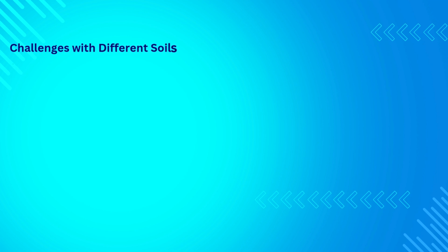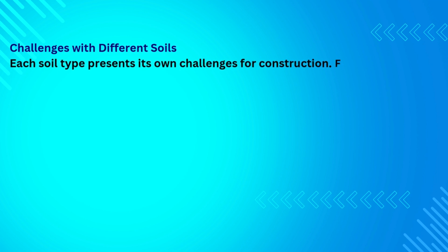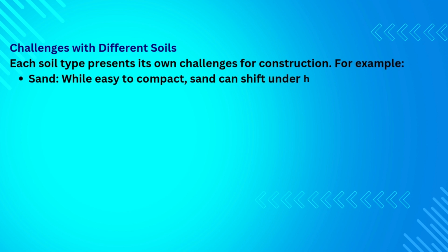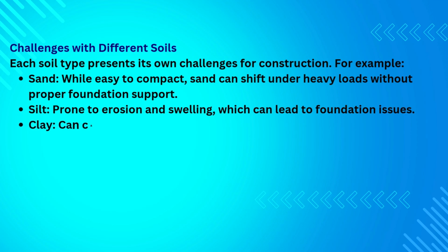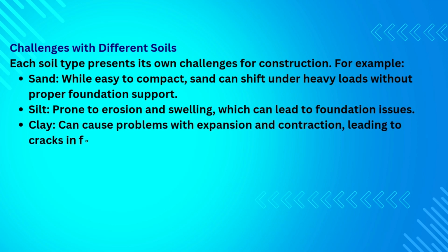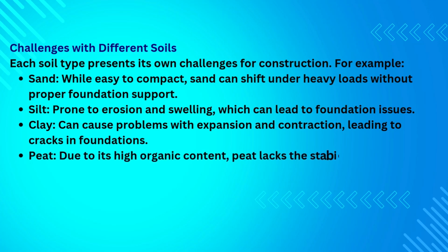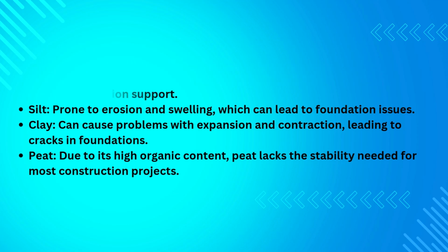Challenges with different soils. Each soil type presents its own challenges for construction. For example, sand. While easy to compact, sand can shift under heavy loads without proper foundation support. Silt. Prone to erosion and swelling, which can lead to foundation issues. Clay. Can cause problems with expansion and contraction, leading to cracks in foundations. Peat. Due to its high organic content, peat lacks the stability needed for most construction projects.